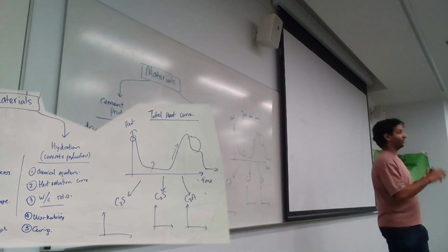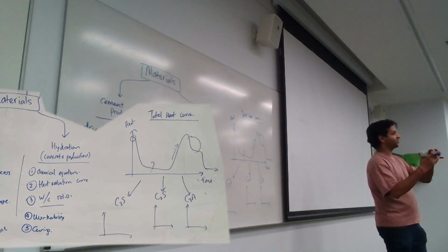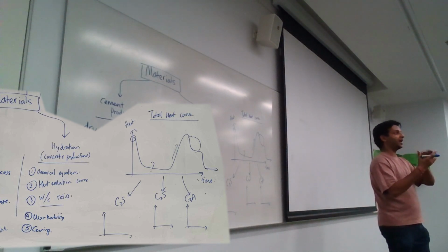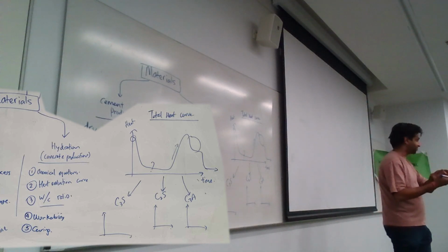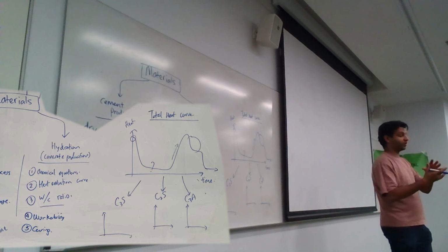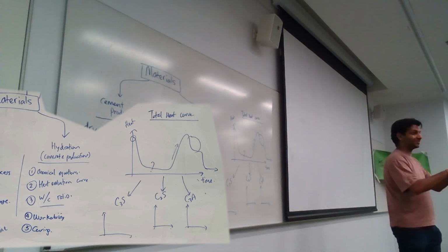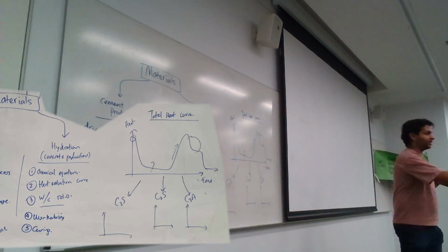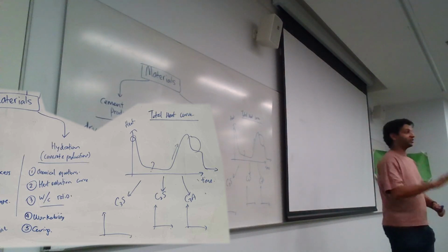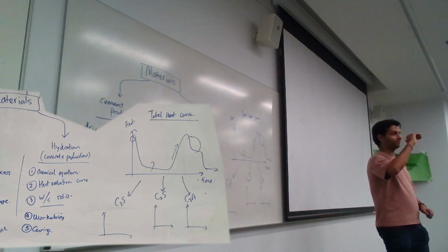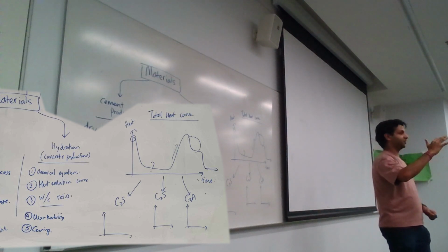See? So I'll say that again. In the mixing stage, if your water cement ratio is too high, the eventual strength of concrete drops. But once your initial concrete has set, if you dunk it in water, the water cement ratio doesn't go up, it stays the same. So it's actually better for your concrete.